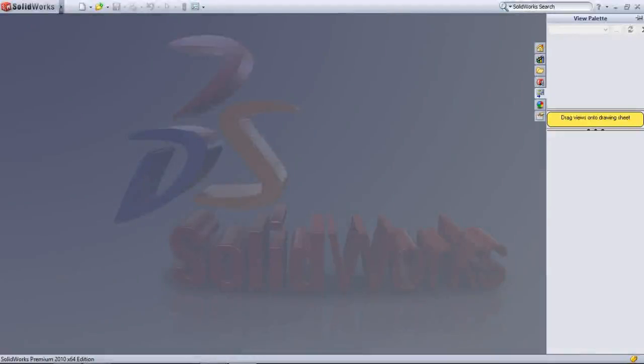Hi and hello viewers. Today I am going to discuss how to design a socket for a hexagonal bolt. Normally, a socket will have to withstand the torque given by the assembler or a tightener of the bolt. So there will be wear and tear on the hexagonal bolt, and you have to consider that wear and tear when choosing the dimensions of the socket.